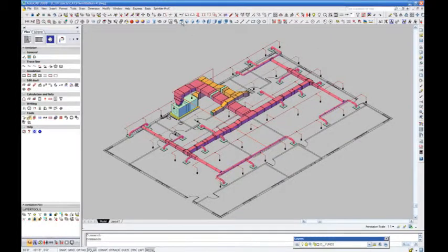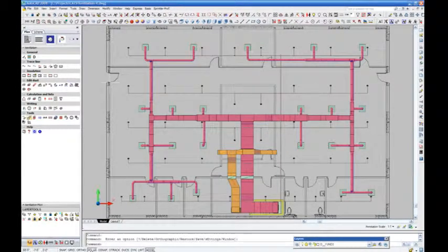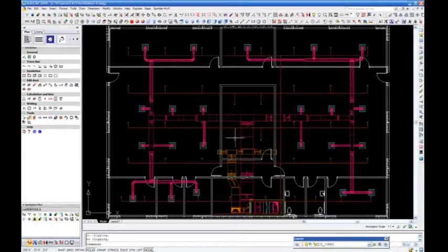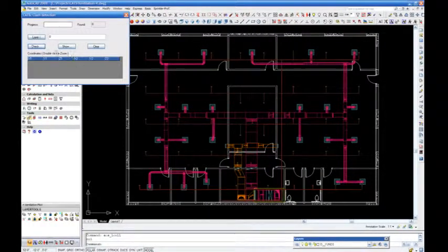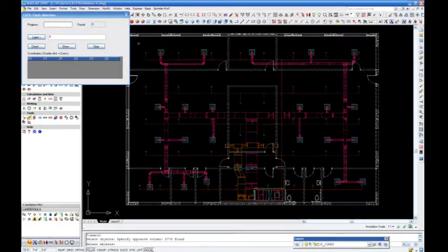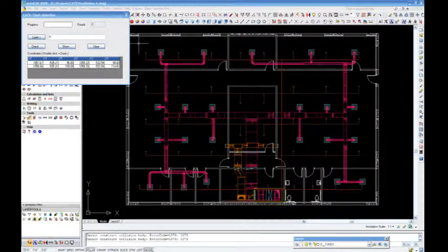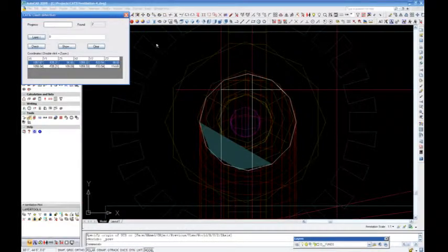We change our view to a top view. We are now rechecking the CAD's clash detection for any missed items. The same procedure will be followed. There remain 2 unresolved collisions. Again, by double-clicking the coordination points, the collision is zoomed to.